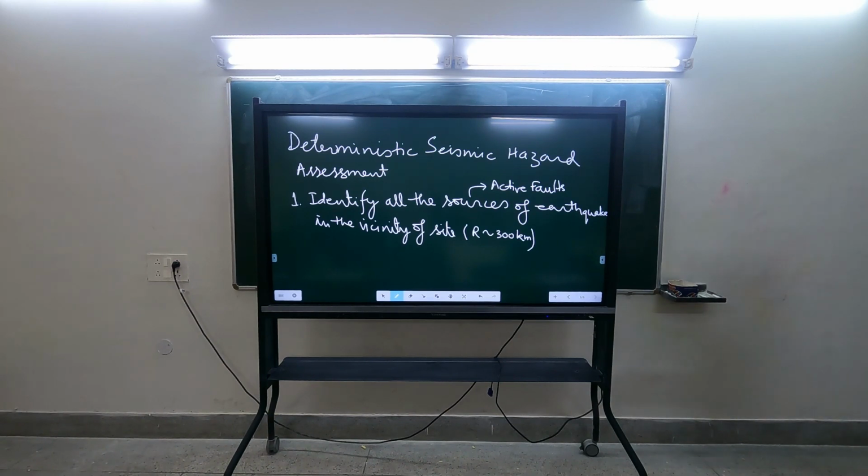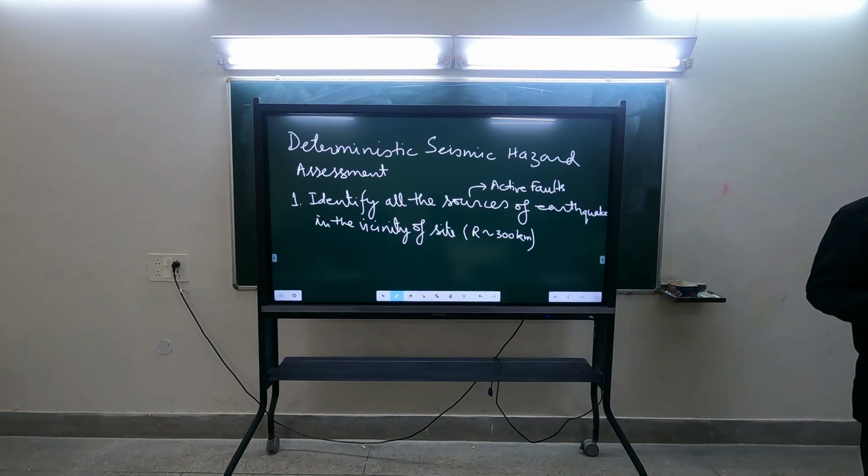Okay, such energy can be generated only with a huge bomb blast. Then you can get that information. Otherwise, these small energies which we are creating by using a hammer or a small impact, sometimes people are using even a truck, okay, to cause that impact. The energy caused there will give very low intensity waves which can't travel those long distances. So this is done to study the local soil conditions, but this can't be used to study the crust of the earth.